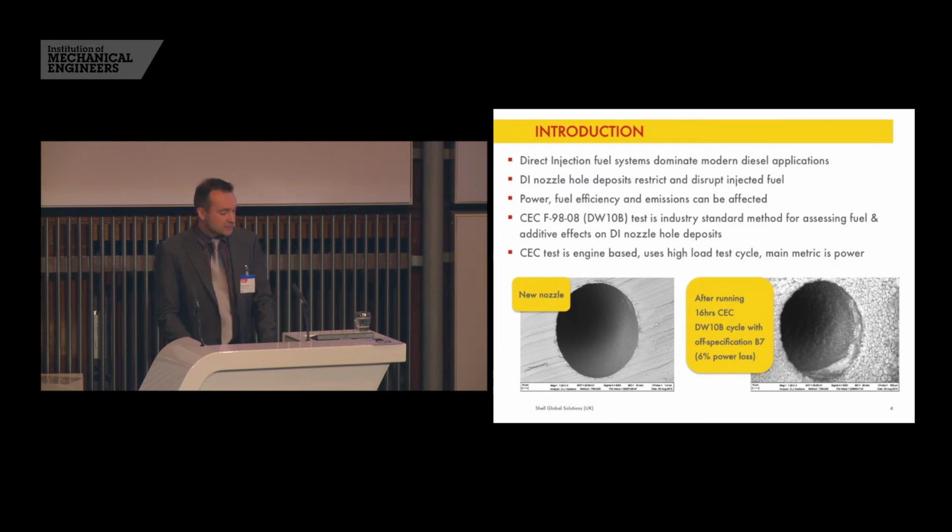So, direct injection fuel systems dominate modern diesel applications, and when deposits form in the holes of these DI nozzles, we can get reduced injected quantity and impaired spray formation, among other things. And in turn, these can lead to power and fuel efficiency detriments, as well as emissions detriments.